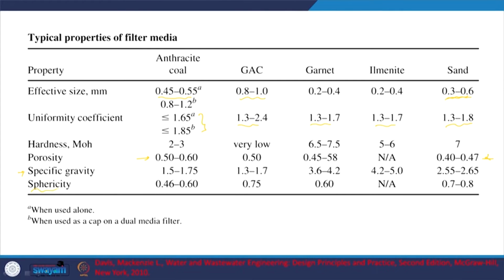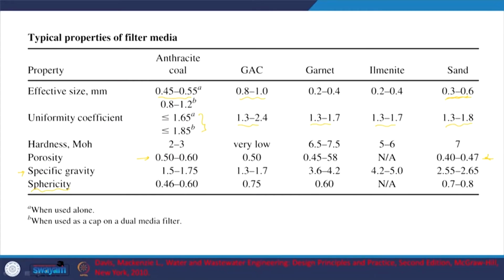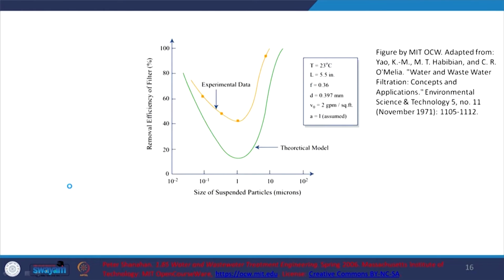Again, why sphericity or such, this is what we talked about when we looked at sand which is well rounded or relatively crushed and irregular, because most of the models assumed that the media is rounded, and thus the mechanisms and the models depend upon the shape of the relevant media. But if it is crushed sand, again you can look at empirical equations or look at the experimental data too, right. So, experimental data versus this, why is this?